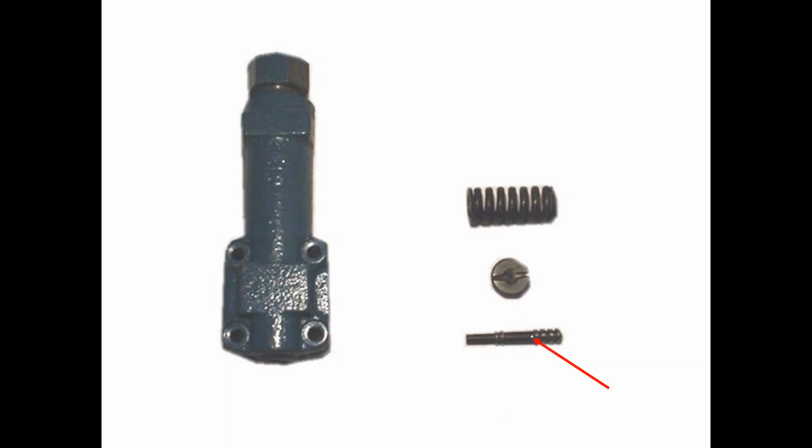Okay. Do you think this has ever happened at your plant? I've literally seen it hundreds of times. The pump gets changed and it fixes it. That's great, but you could have fixed it a lot cheaper and a lot faster, because how long would it actually take to do this? How long would it take you to remove these 4 Allen bolts, these Allen screws here, open this up, dump these out, and look at this hole?